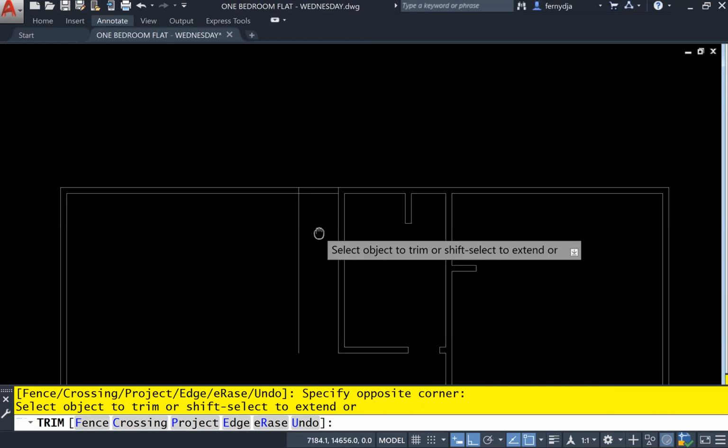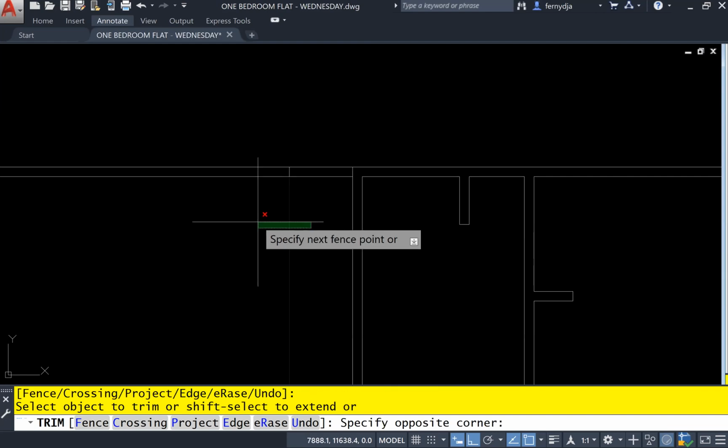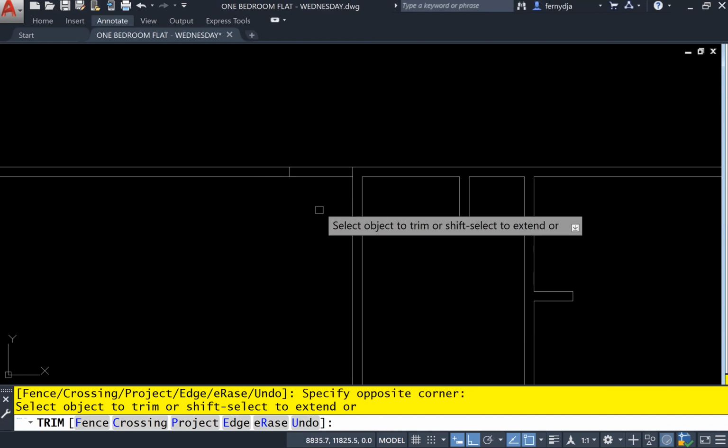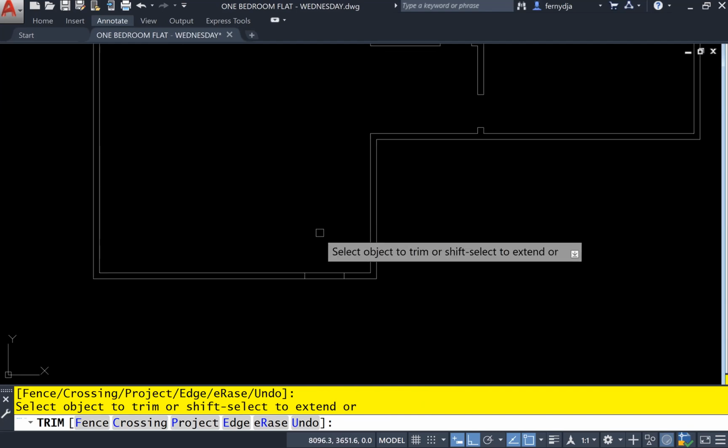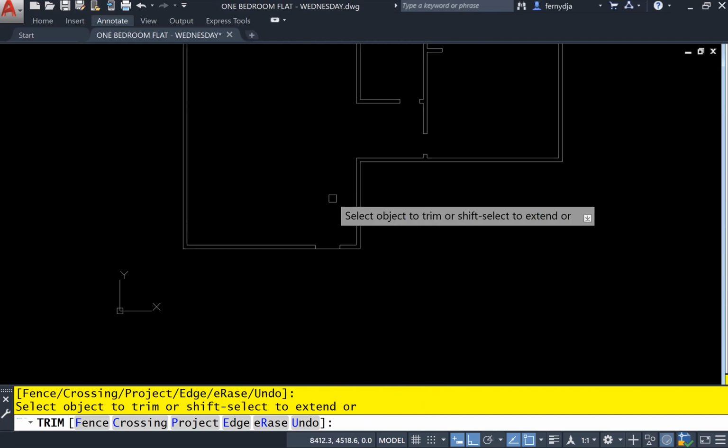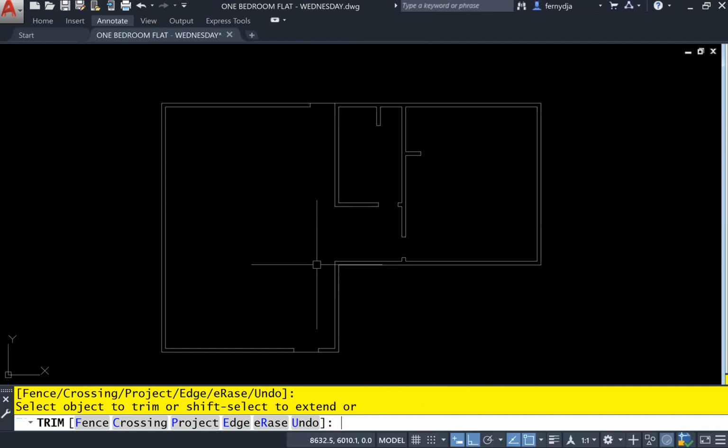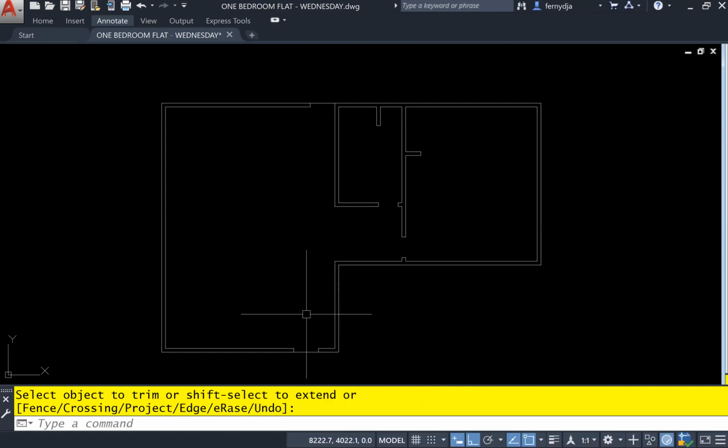However, when it comes to the back door and the front door, we trim this line, but we only trim the inside line for front door and the back door. And the reason for that is because the floor level is higher than the ground level. Ground level outside is below. So that line indicates that you're actually stepping up. So it's difference in elevation.